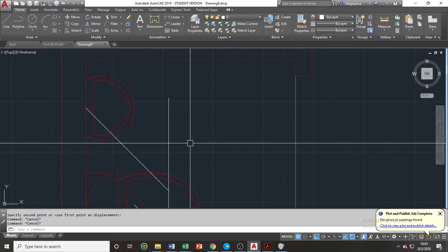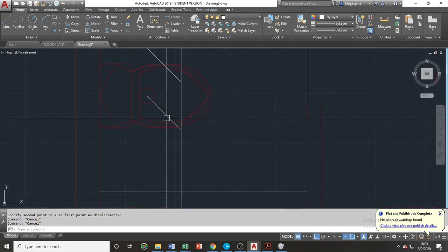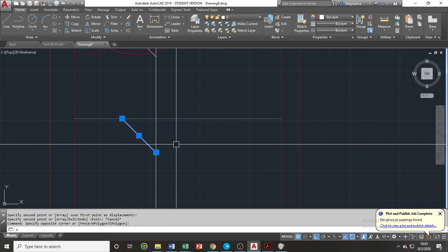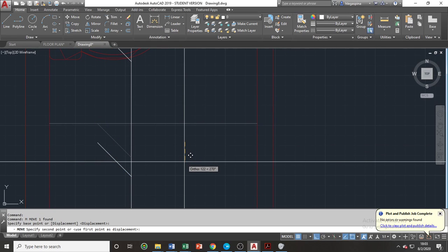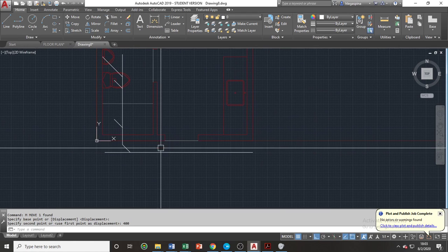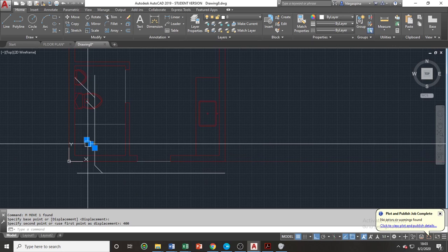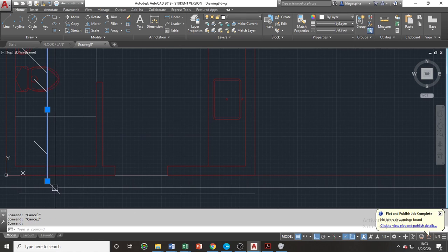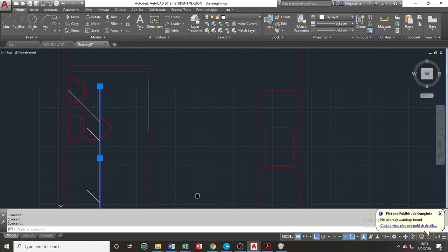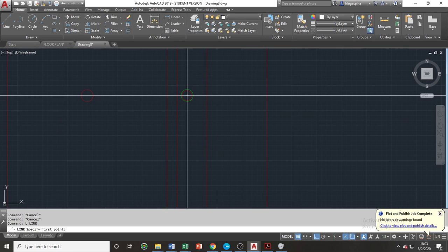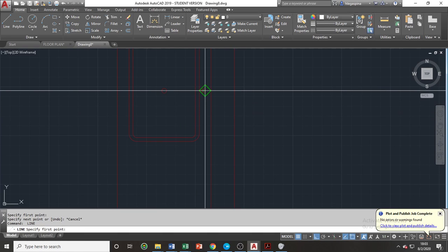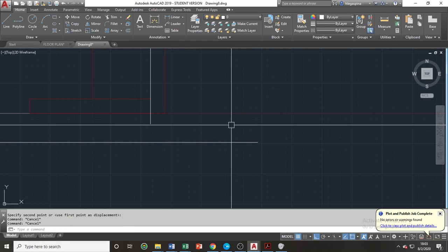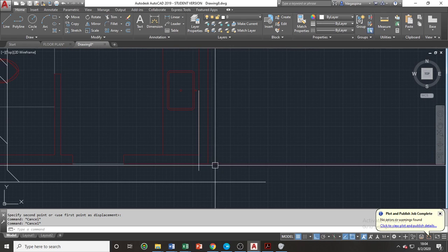The endpoints of our pipes should be provided with clean outs for maintenance purposes. And also we need to provide connection coming from our floor drain. We also need to provide drainage for our sink, which should be connected to our main sanitary branch as well.